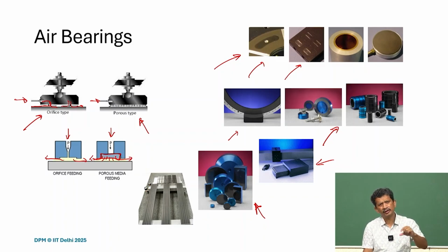But we also need to understand that the air film also supports the load, and it also creates a stiffness. So, we will be talking about all those characteristics, and there might be some doubt about the application, but once we know the physics and how it works, we realize that they are very good elements and can be used for developing any kind of motion stages, not only for precision application, but for other kinds of systems as well.